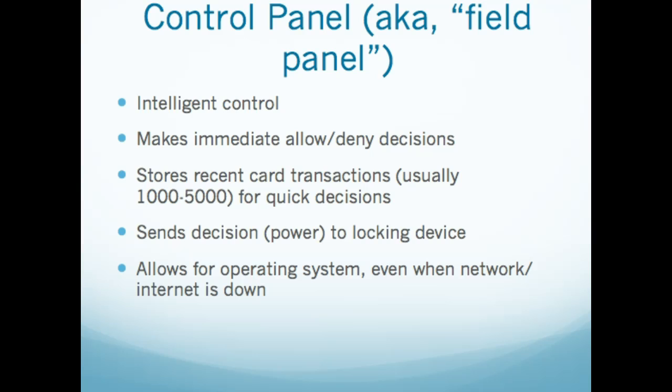Control panel, hugely important. In our projects, we're going to use a 2-door controller. And the reason I say that is for every 2 doors that you have on your access control, if you decide on our warehouse to put card readers anyplace, for every 2 doors, you're going to need to have a panel. You're going to want those runs to be short, right? The wire runs between them to be relatively short. So you'll want to position your panels in the warehouse close to where the readers are if you can. Although our warehouse is not too big, so it shouldn't be a problem.